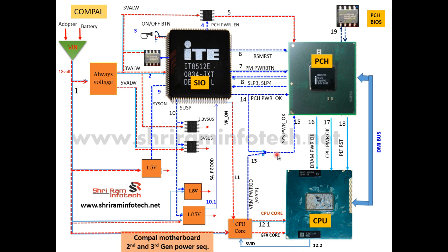If you check this voltage here, 3 volt, that means you do not need to check all these other voltages. If this signal is coming, that means the entire power planes are perfect and working all right. If this voltage is not coming, then the system will halt.